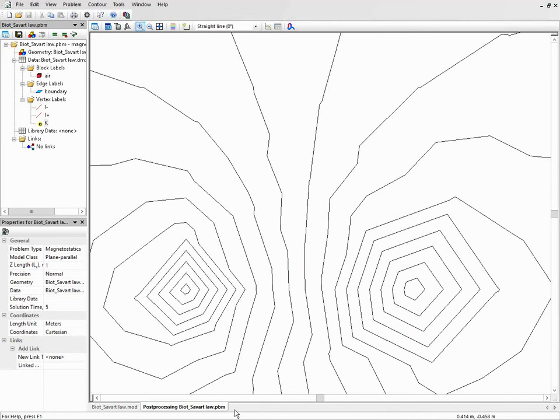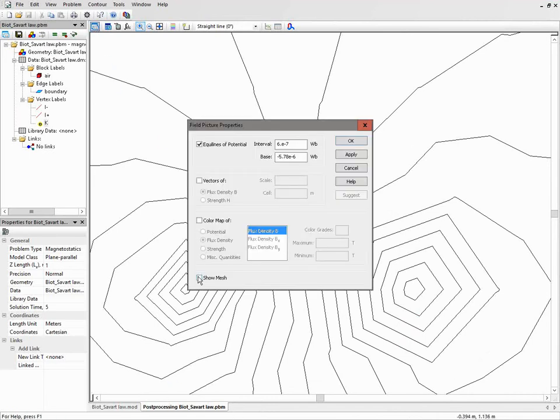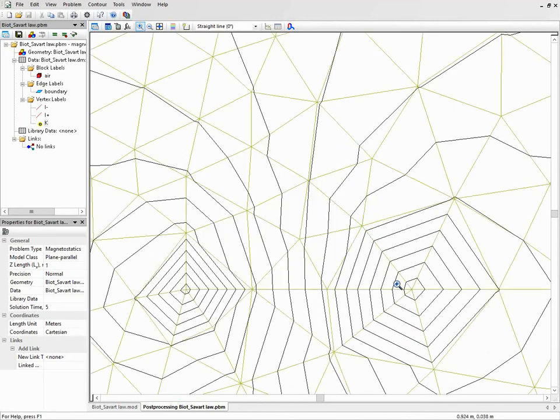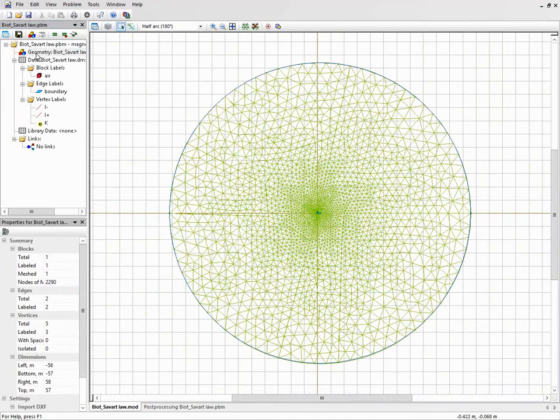That's because the finite element mesh is not rightly sized. When QuickField builds the finite element mesh, the logic is simple. For large objects, QuickField chooses large element size. For small objects, small element size.